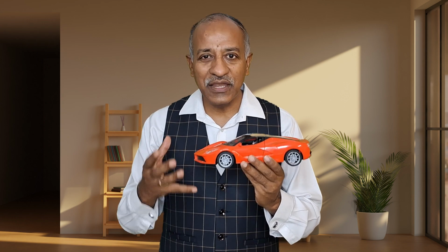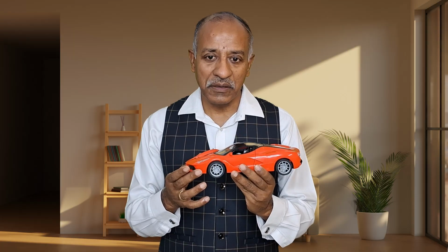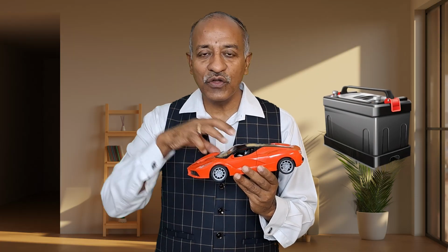Another point here is with respect to design for manufacturability, assembly and service. Assume that we have made a design and now we are putting it into production, but we are not able to do it because the design is so complicated. Even if we could make it, maybe when it goes to the service part and we want to change any part, we find it very difficult. For example, maybe there is a battery inside. First of all, you find it difficult to put the battery in at the time of assembly. Then when we have to change the battery, it is very difficult to remove it and put in a new one. It means the design may be very good, quality may be very good, but the implementation part is very difficult.